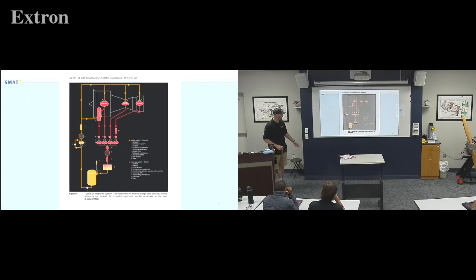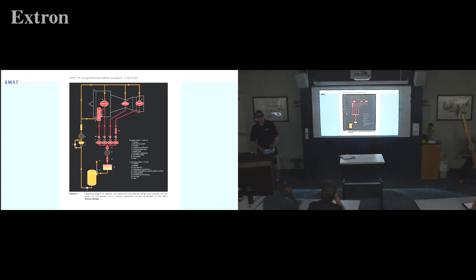All right, I think this image might show up somewhere in your near future. So you've got the turbine engine here, right? What do you suppose all those red things are? Fuel pumps? Oil pumps. What kind? Give me a little more specific. Scavenge pumps, yeah, because typically we've got a bunch of scavenge pumps and one pressure pump. So they're sucking the oil out. They're sucking the oil and air out. It's going to go through, I don't know if I can even read that. That says scavenge filter, heat exchanger into our oil tank.